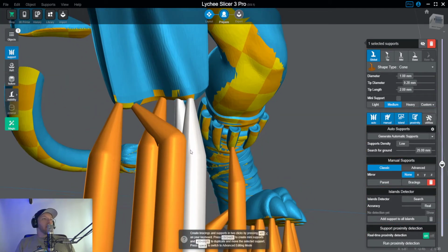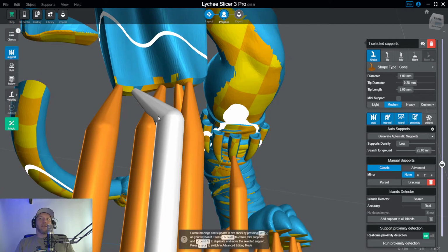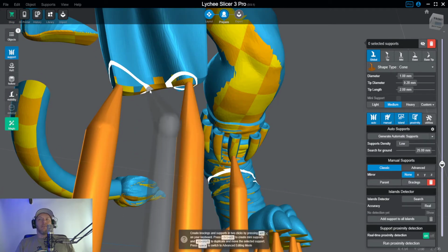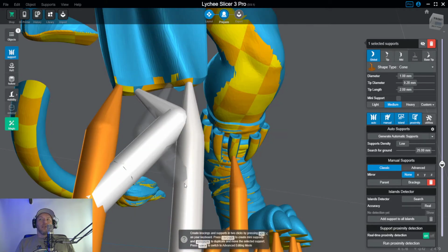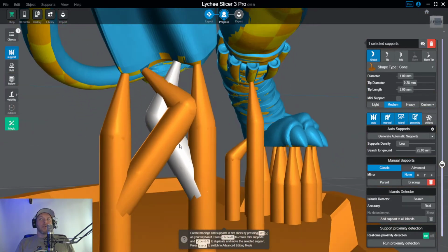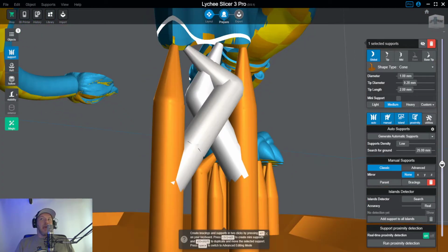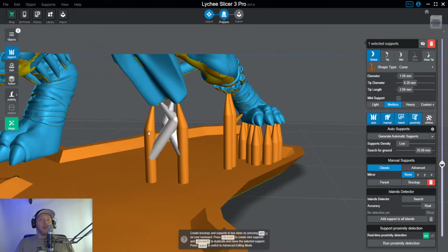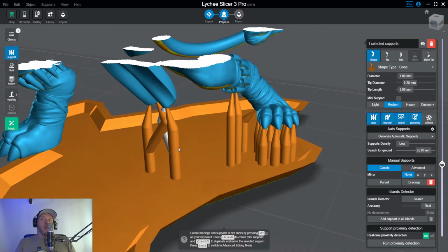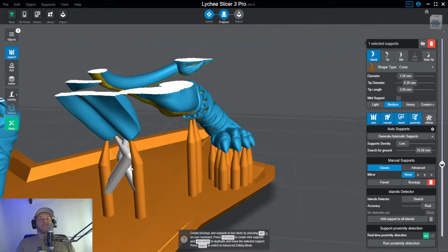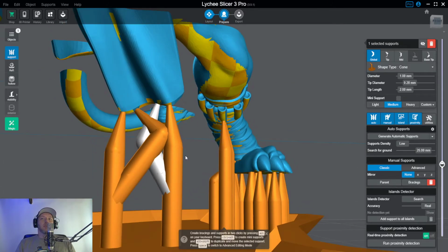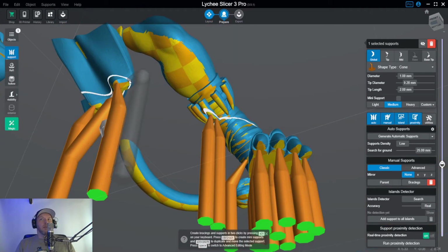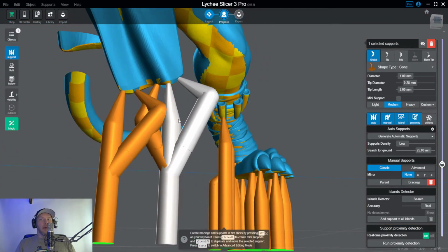Did I maintain priority 3? Is it efficient? Nah, it's not really efficient. I think we could probably get away with making some sort of branch here where we cross it over, turn the supports into bracings, and then add extra supports without having to run all the way down. It's marginal. It may not be worth going back and solving, because the amount of resin saved is such a small amount. But if we get into those good habits now, it's worth it.